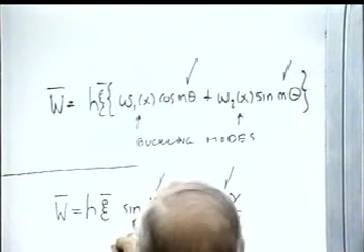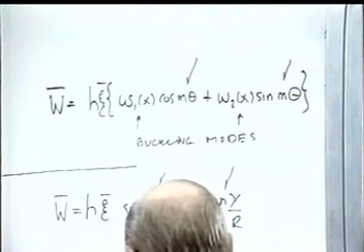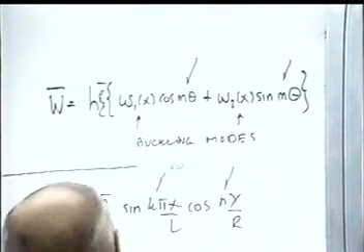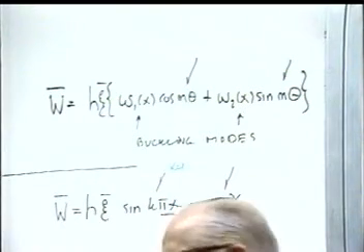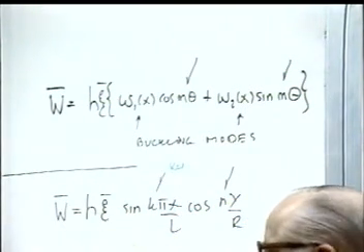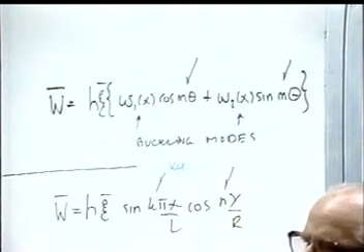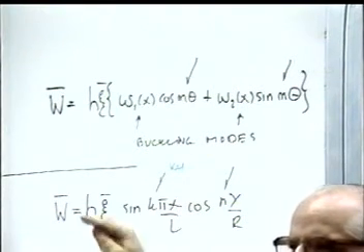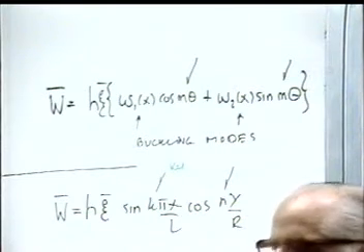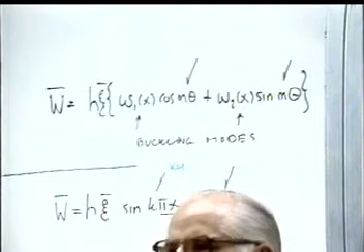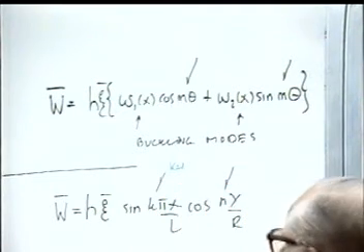And what I did there, I chose this k to be 1, because experimental measurements indicate that in the type of shells that I have looked at, that is always the biggest imperfection, with k equal to 1, just half wave in the axial direction. Apparently, if you make shells, you get a bowedness either inward or outward into the shell. Okay?